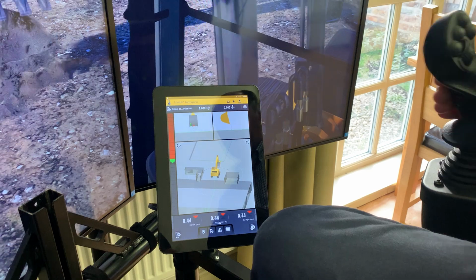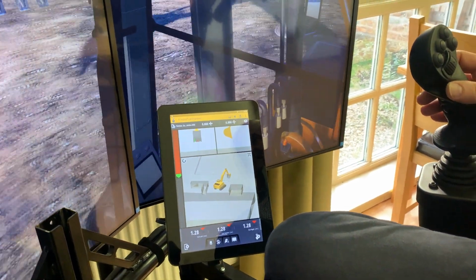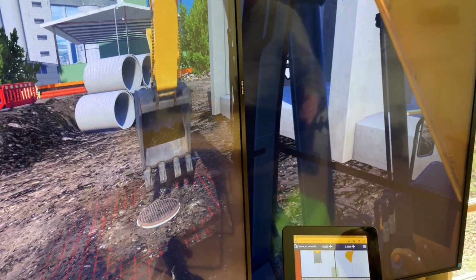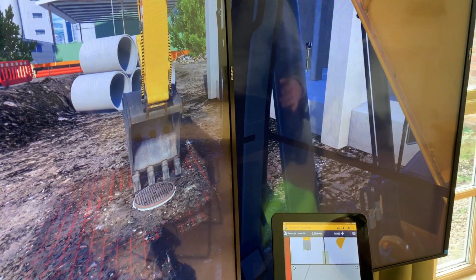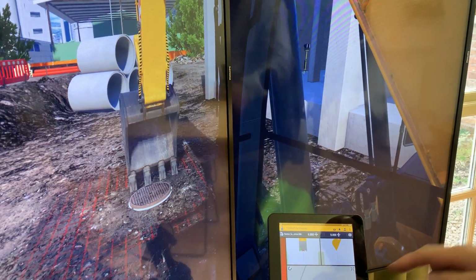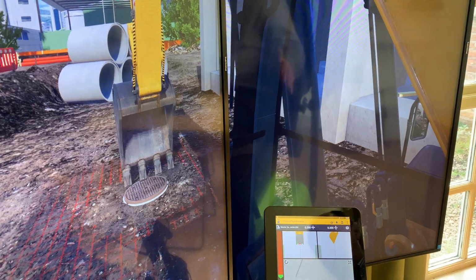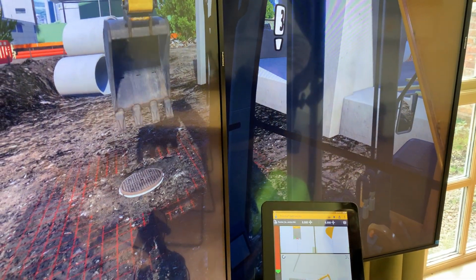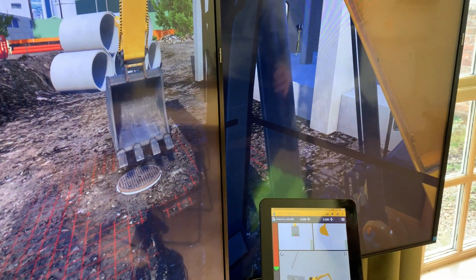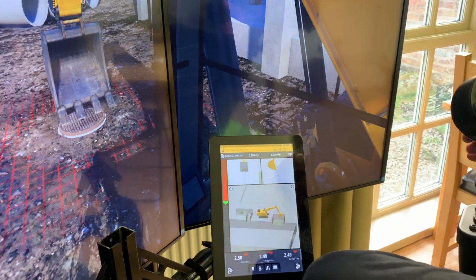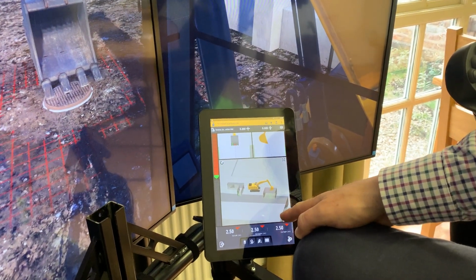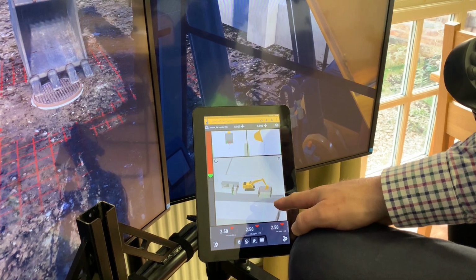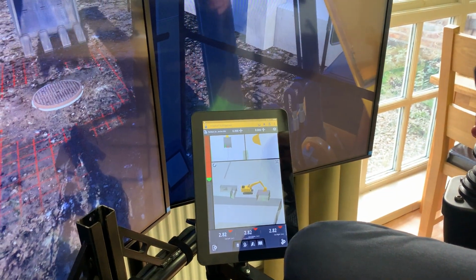There's a few other things you can do. Maybe to test the bucket, you can place the cutting edge on the inspection chamber here. When you balance down on there, you'll see 2.5 meters of cut. If you change the bucket into a different orientation, place it on the lid again, you're getting the same cut fill values. If we had the wrong bucket, those values wouldn't correspond. So it's a good check to do there.